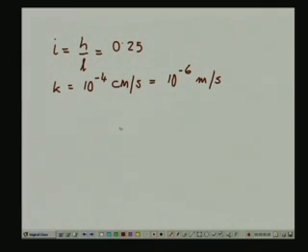I should draw your attention to my usage of centimeter per second as the unit of permeability. Although we are in general sticking to SI units in this series of lessons, in this case we are using centimeter per second because that is more commonly used in the profession, and many practitioners are used to seeing magnitudes of permeability in that unit.